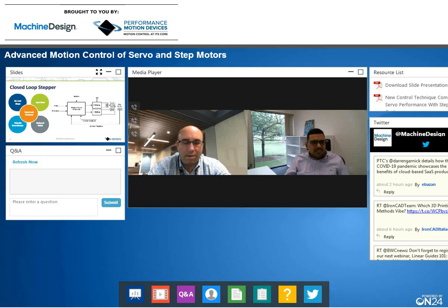Ty, do you want to add anything to this? Yeah, if I could jump in. I think the key thing is there are many solutions that are a stepper motor with feedback that allows you to know if something went wrong, whether you got to the position you thought you were getting to, whether you slipped counts, things of that nature. Those are closed loop systems, but they're kind of blind systems.